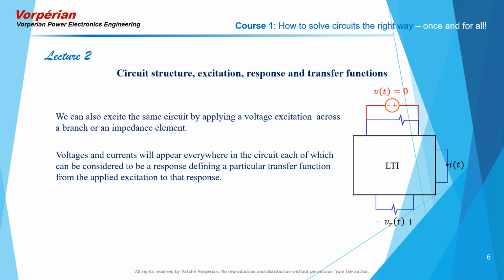So now when I set this excitation equal to 0, the voltages and currents everywhere will go to 0. And the circuit will eventually go back to rest. Just like that. However, we know that a voltage source with 0 value is nothing more than a short circuit. And when you do that, you replace the voltage source of value 0 with a short circuit. In this case, you end up shorting the top resistor inside the structure, and thus you modify the structure.